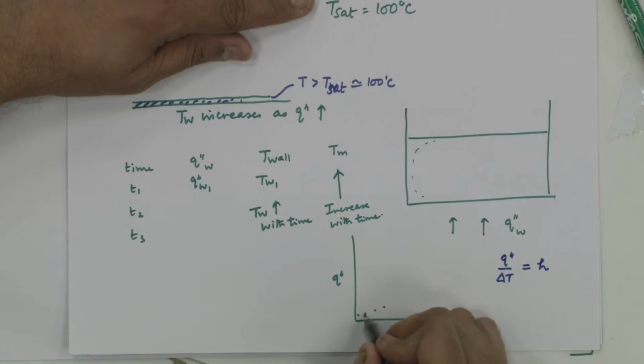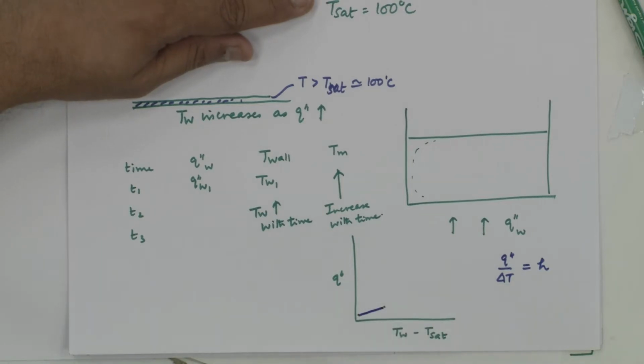So, low heat transfer coefficient, the slope is going to be very small. You would see something which is like this, a line which is almost parallel to the x axis, slightly inclined by a few degrees, and this is what is the natural convection region. And you have your single phase heat transfer correlations that have been developed, which you can use to predict the heat transfer coefficient in this part. Okay. Now, the activity for boiling is going to start.